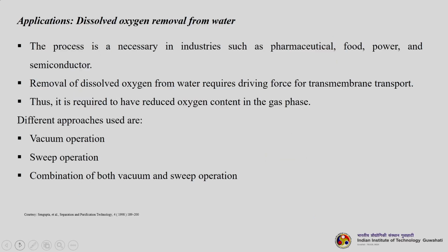Another application is dissolved oxygen removal from water. This is a very important application in industries such as pharmaceutical, food, power and semiconductor. You need to remove the dissolved oxygen from water. Removal of dissolved oxygen from water requires a driving force for transmembrane transport, so it is required to have a reduced oxygen content in the gas phase. Different approaches are used. You can have a vacuumized operation, you can use a sweep gas based operation, or you can use both vacuum and sweep together.